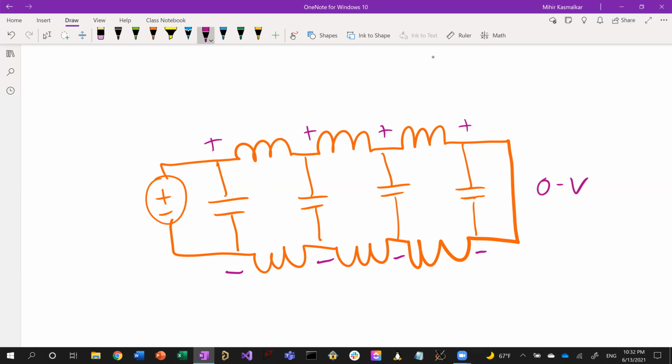Now this last capacitor is charged up, but it's going to want to discharge through the short circuit, because you've just connected a wire across the leads of the capacitor. It's even better than an RC circuit. It's just going to straight up discharge through the short circuit. And so you're going to lose this voltage that's built up on the capacitor as it discharges.